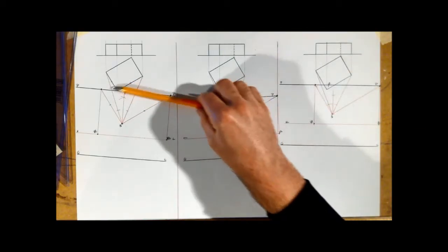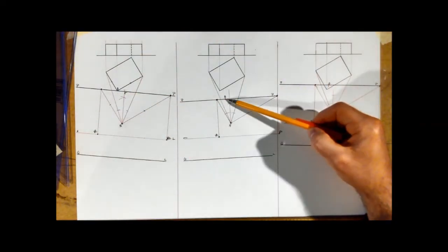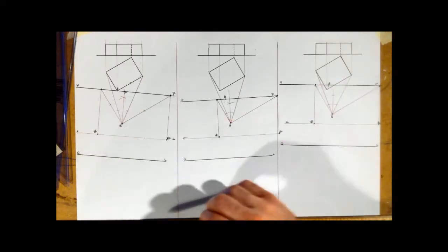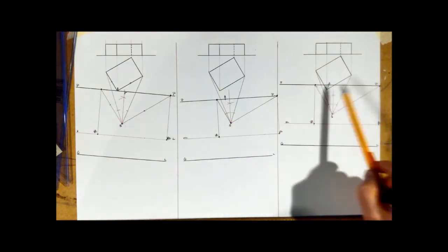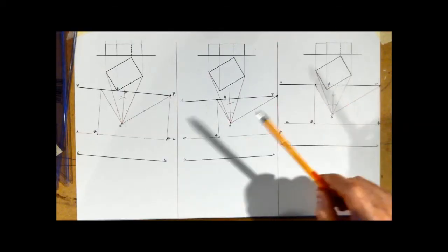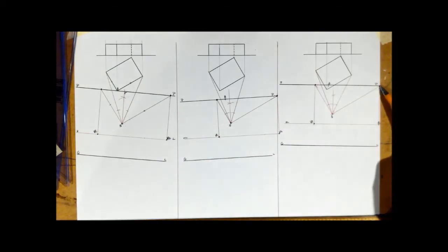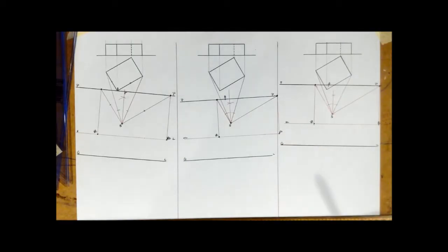So as you can see, our picture plane in this case passed exactly through the corner A, which is right on our actual object. The picture plane in this one is actually in front of the object. If you imagine the picture plane, it's like a piece of paper that's going up into the air like that. Okay, and in this case our picture plane is actually going through the object, and we can see that it's going to pass through at 2 points, this one and this one right here. Now obviously I just managed to fit it. I was working out the page beforehand, a little bit tight for space, but I just managed to fit it. This one went slightly into the other page, but it doesn't really matter.